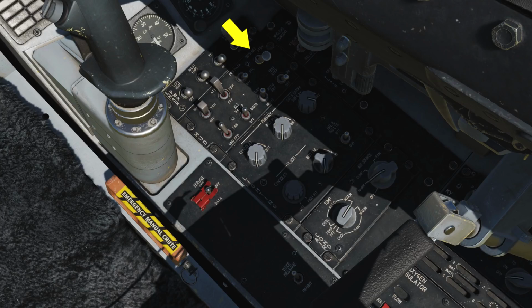The depressed reticle switch controls selection of the primary or secondary standby reticle on the HUD. Standby displays the standby reticle and removes all other HUD symbology. Primary displays the primary reticle but does not remove any HUD symbology. Off does not display either reticle.